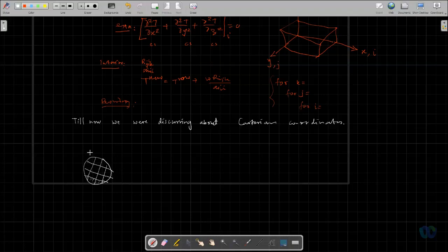Okay. Suppose you are using the finite difference method, then you can transform this domain. Now x and y can be transformed into xi and eta, and that transformation will be such that you get Cartesian coordinates. So the equations in x and y, or r and theta, can be converted into xi and eta coordinates in such a way that you get a rectangular, Cartesian coordinate system, and then you can solve the problem. Okay. So suppose there is a non-specific spherical coordinate, but a complicated domain.